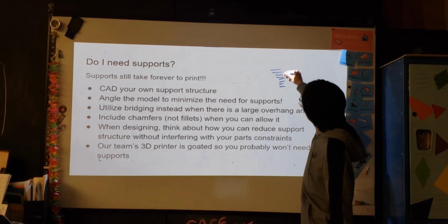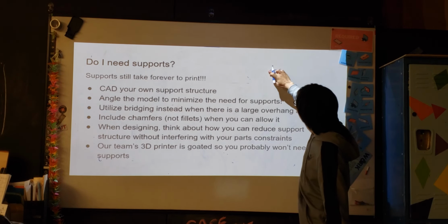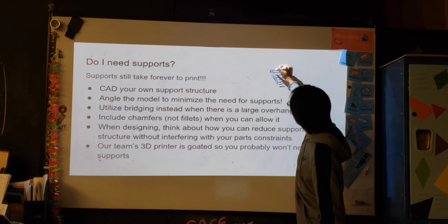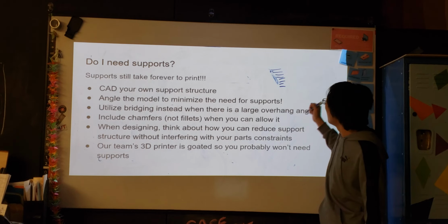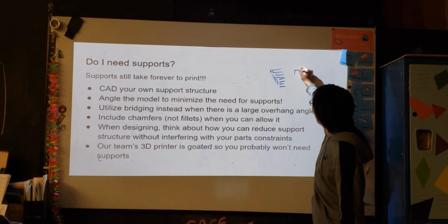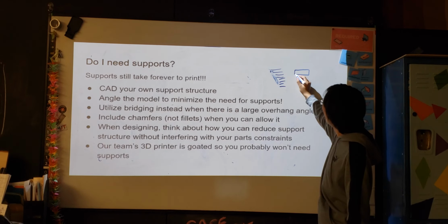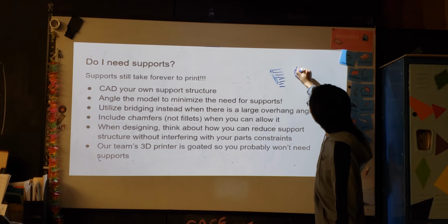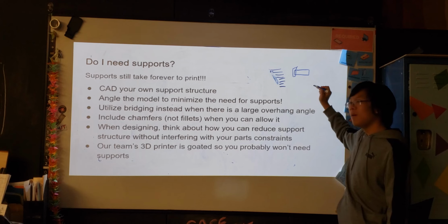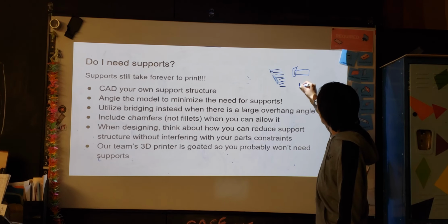But what is it doing here? There's overhang, right? And this section of plastic right here is not being supported by anything. And then let's go even closer to like the top view. And this is what the section looks like from the top view. And this section of plastic is not even supported by anything. So it's gonna be worse quality than if you have like this.